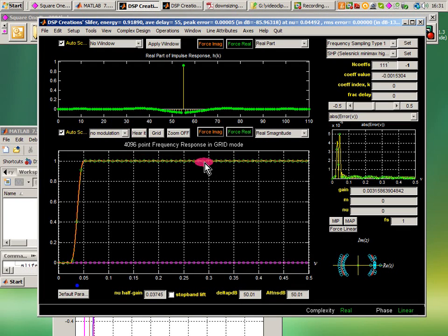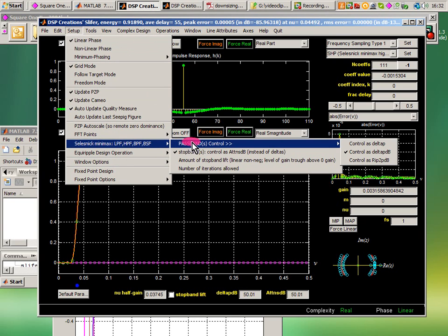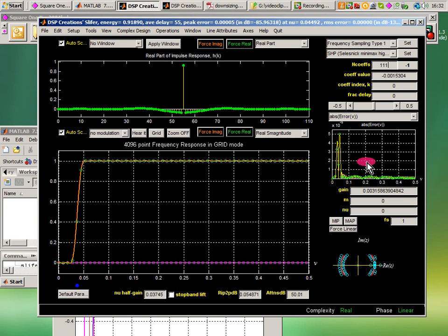Well, I'm aware that there's another solution put forward by a colleague who says it can be done with 75 coefficients. Well, that's true, but the interpretation of this passband has to be changed. As is often the case in MATLAB calls, the ripple is described in terms of something I'm going to change it to here, peak to peak ripple, and it's going to be measured in dB.